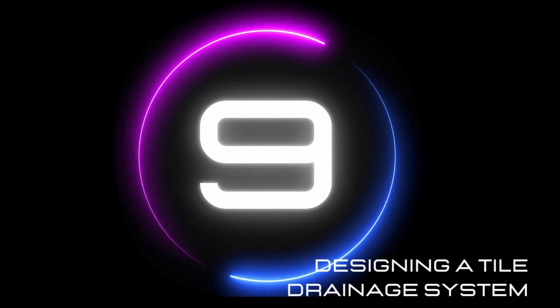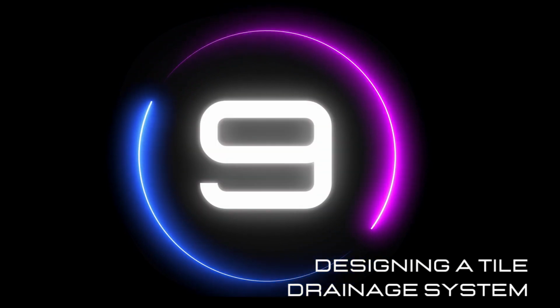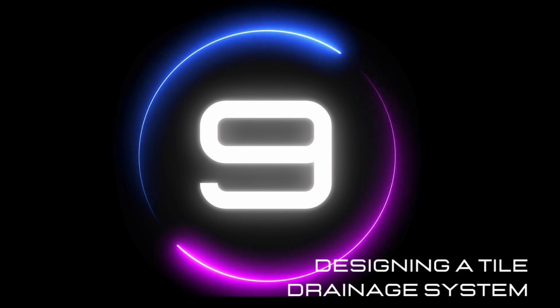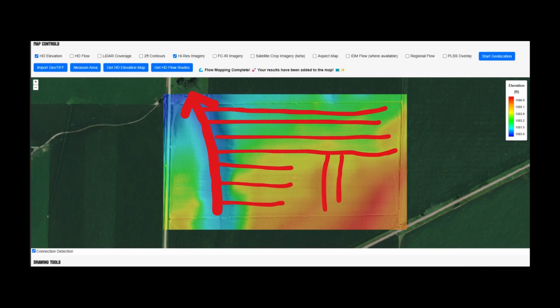Geo-Surface Quick Start Guide Part 9, creating a tile drainage design using Geo-Surface Designer. In this tutorial, we will attempt to design a tile drainage system to target some low areas in this field that are prone to drowning. We'll look to place a main running north-south with the outlet at the north end. Then we'll determine whether the proposed layout is viable by testing the runs.